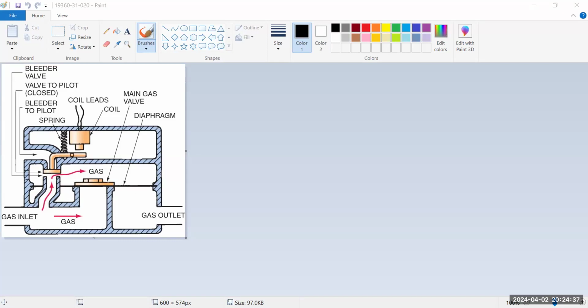All right, so your contactor, your relay, the gas valve, those are all electromechanical. And then we have electronic controls and devices. These have circuit boards on them. They could be at 5 volts DC, they could be at 24 volts AC, they could be at 120 volts. Basically anything with a circuit board on there, you can consider that an electronic component. And we do troubleshoot a lot with circuit boards.